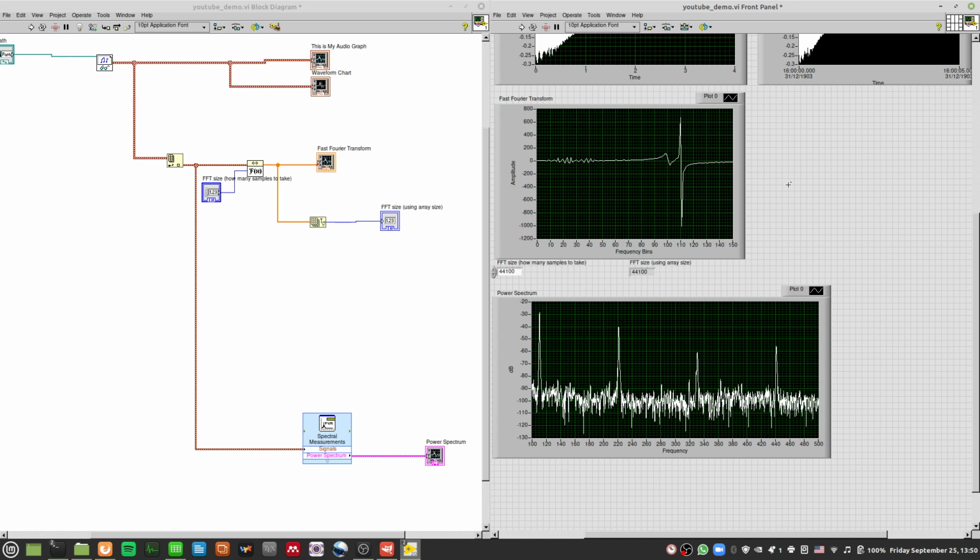However, that only enables you to get the first 1 second, because that's 44.1 kilohertz, or 44.1 thousand samples, and that only gives the first second. If you want to analyze a very long waveform, you'll need to do some division.